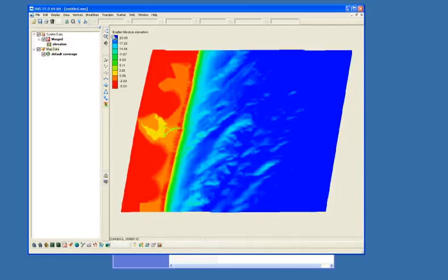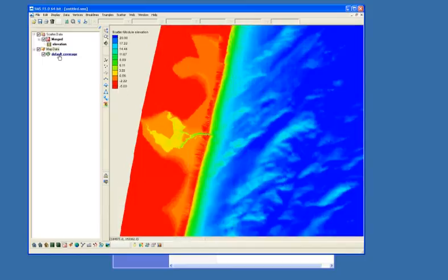All right, and so what we want to do is basically the same thing that we did before. So we need to create a coverage that's for a CMS flow. You can either use the default coverage, you might want to rename it something that you can remember what is in that actual coverage, and then you can right-click and set the type to be Models CMS Flow.